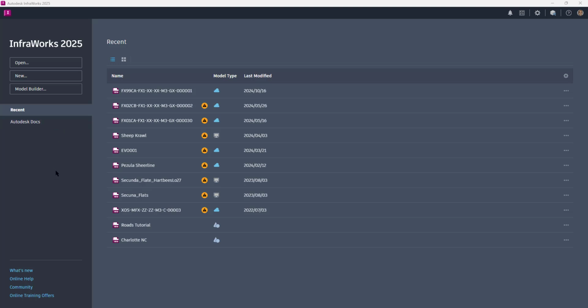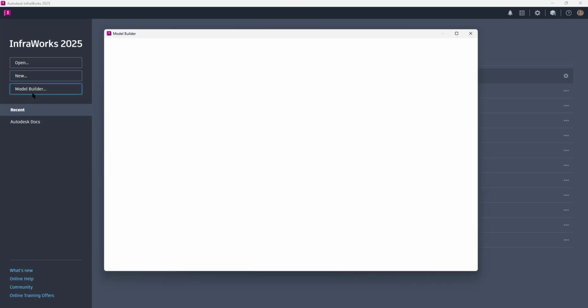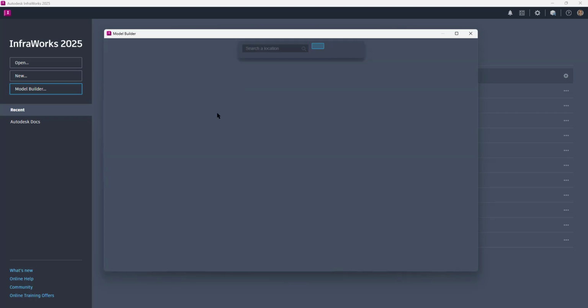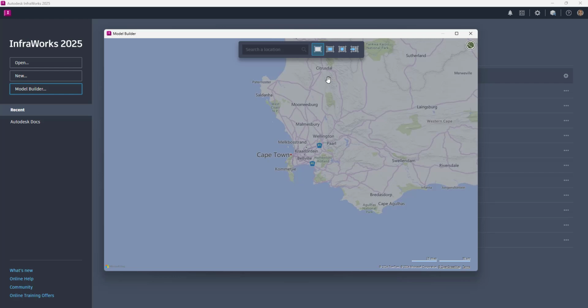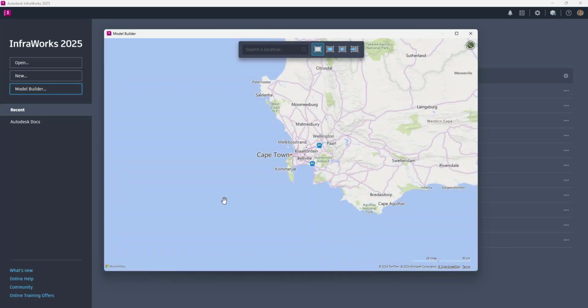We are an Autodesk reseller, and today I'd like to focus specifically on the South African coordinate system in Infraworks, Civil 3D and Revit, and how we work with that over here in South Africa. Just as a background, in South Africa we work with a left-hand coordinate system definition, and it makes our life a little bit difficult within any design software that we use, especially the interoperability. So I'd just like to show you how that works.